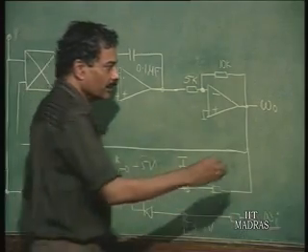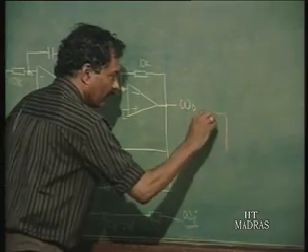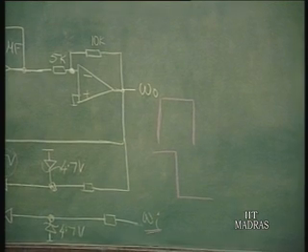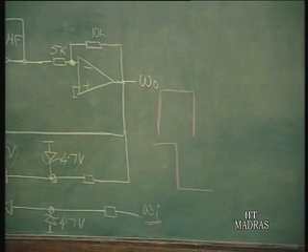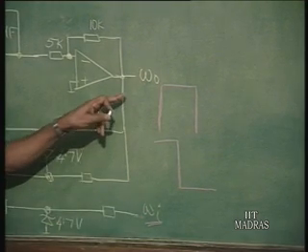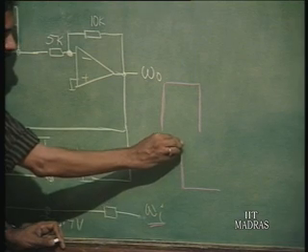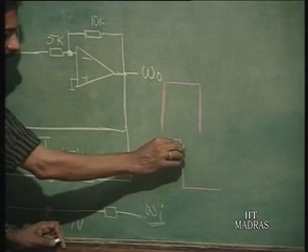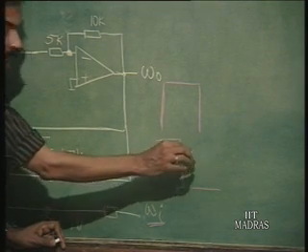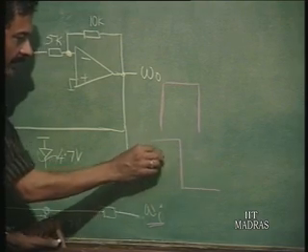And when the locking occurs, you can clearly see one waveform, if it is like this, the other waveform is going to be like this, indicating a 90-degree shift between one and the other, in case the incoming frequency is the same as the free running frequency. This also we see, and we can see that when this incoming frequency is further changed, the phase shift will change around the 90 degrees, going towards 0 and 180 degrees. Okay. This also you can see, 0 on this side and 180 degrees on this side.